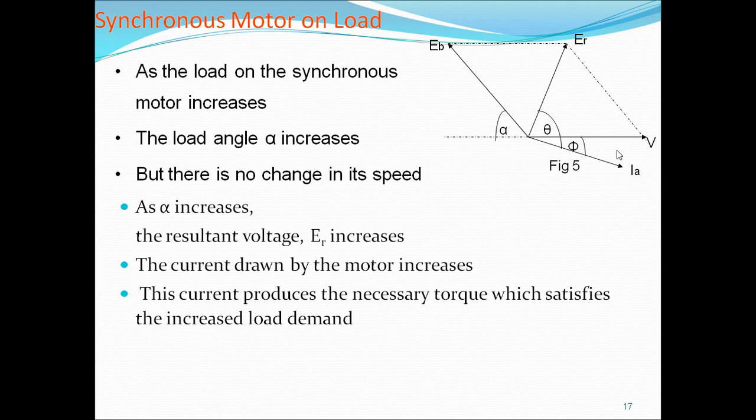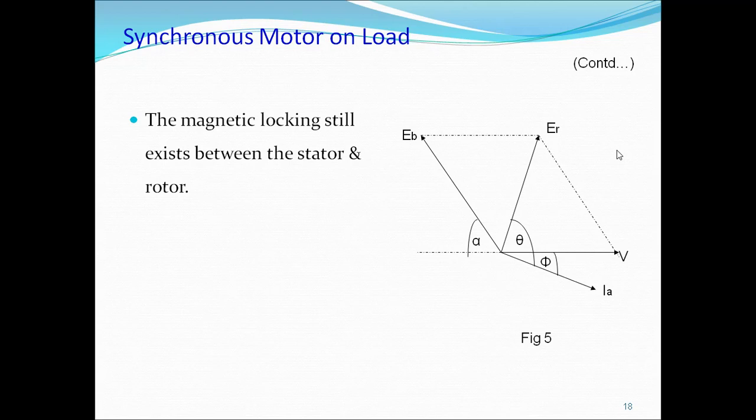So when the motor is on load, the rotor progressively pushes to a new value of alpha. The rotor progressively tends to fall back in phase by angle alpha. That means the angle changes, but the motor continues to run at synchronous speed only. The value of load angle depends on the amount of load to be supplied by the motor.